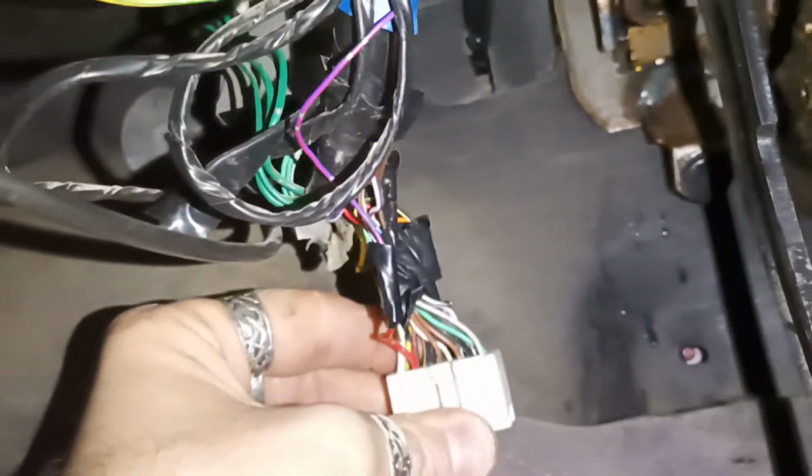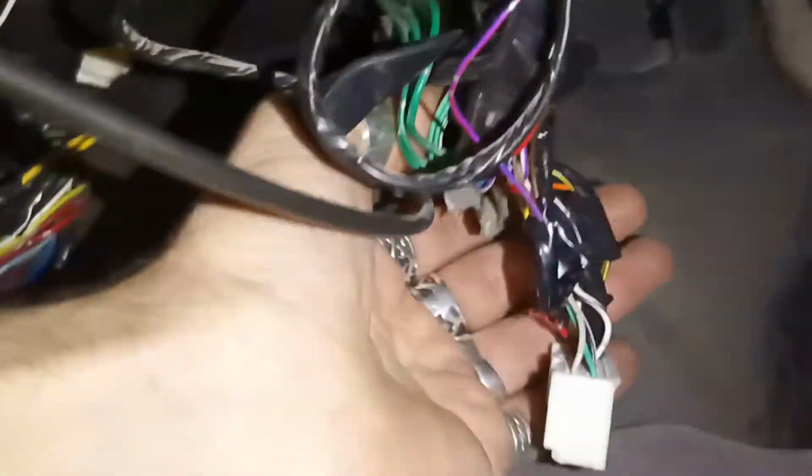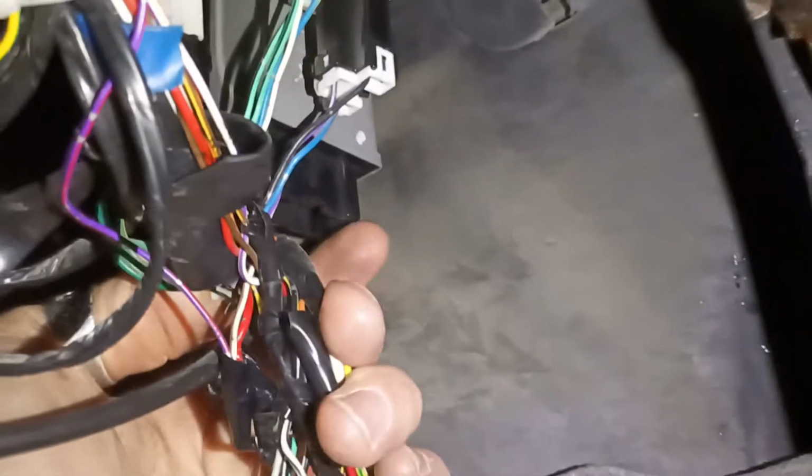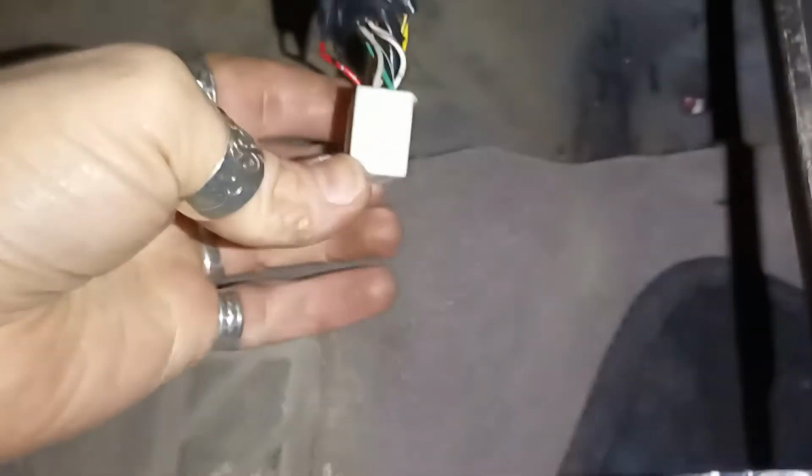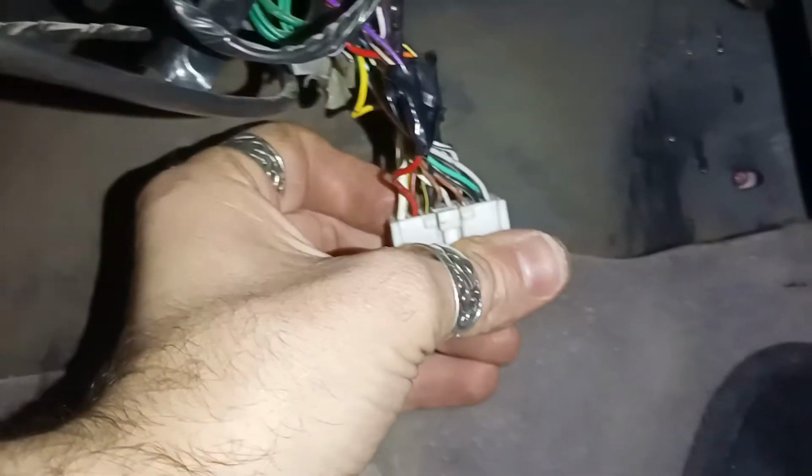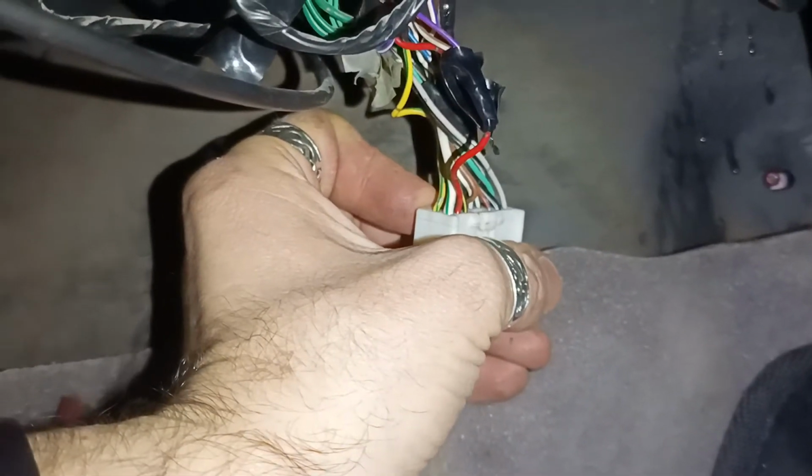The module, as you can see, is actually here. It sits here happily. Next, what you need is the door signal. I have disconnected this connector from the biggest thing, the silver thing here. That's the door lock timer unit, and from it you need this red cable.